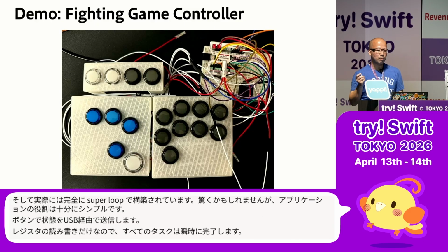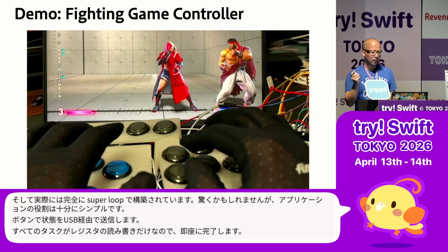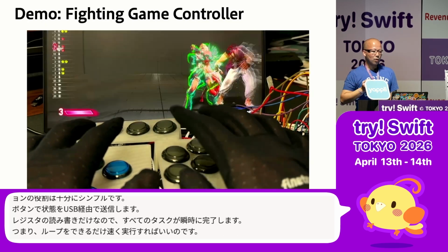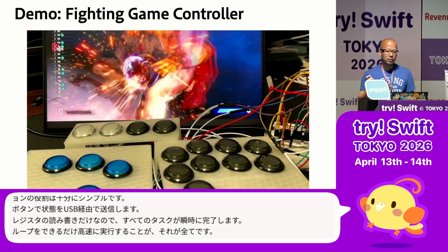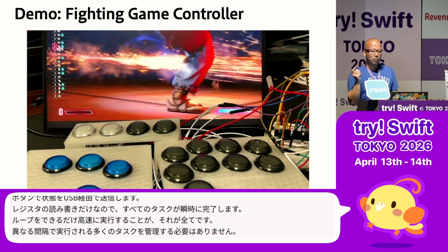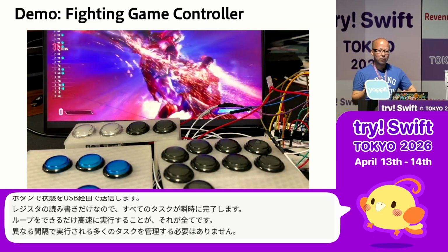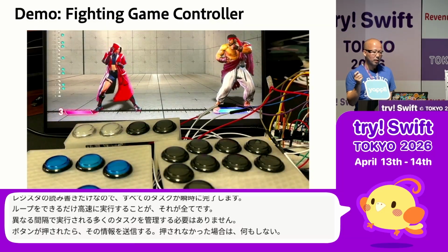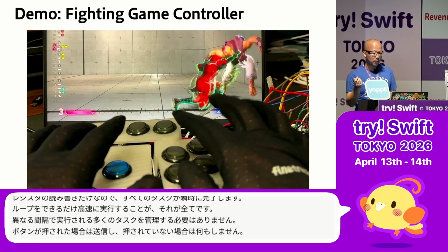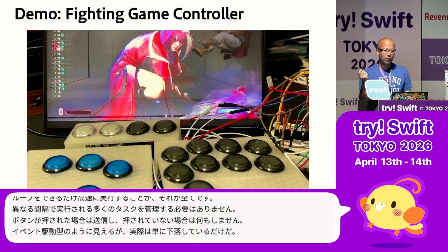So running the loop as fast as possible is all it takes. There's no need to manage multiple tasks running at different intervals. If a button is pressed, send it. If not, do nothing. It looks event-driven, but it's really just polling. That's why a super loop is enough.